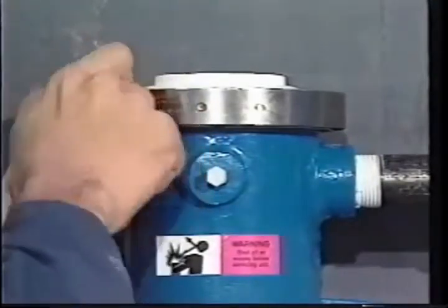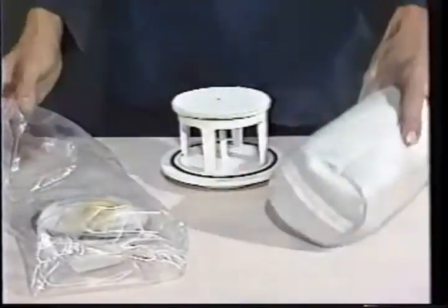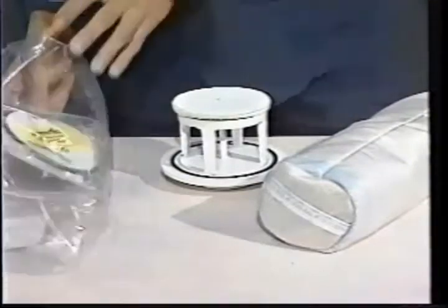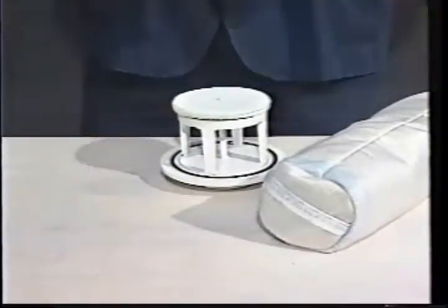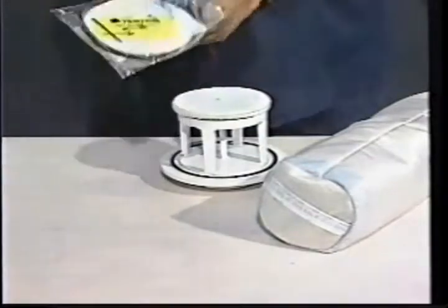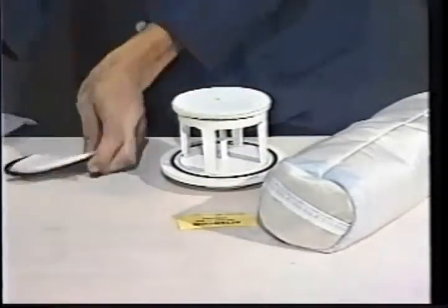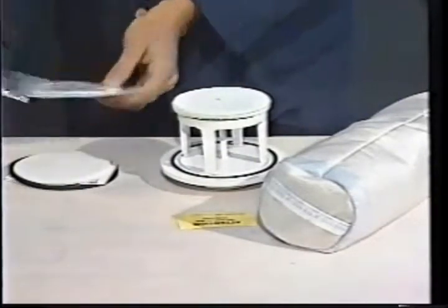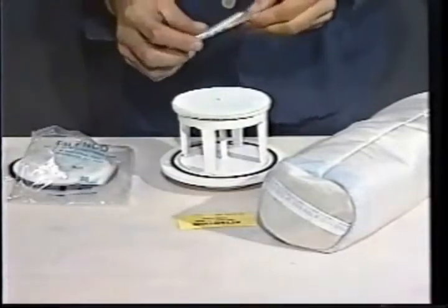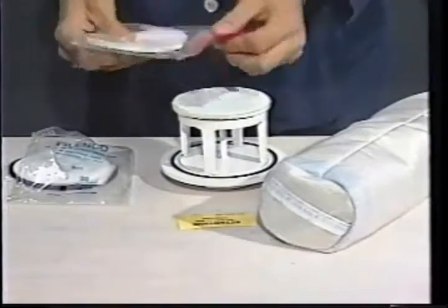When it's necessary to replace filter elements, Filenco offers a 5-part filter fix-it kit, which includes a new bag of desiccant and 2 sets of filter discs. The first, for units made before 1993, are solid and sandwiched between 2 stainless steel screens. The second fits units manufactured after 1993. They have holes in the center, so the lower screen can be screwed to a threaded stud. This firmly secures the filter discs to the cover and spacer, or spacer alone.